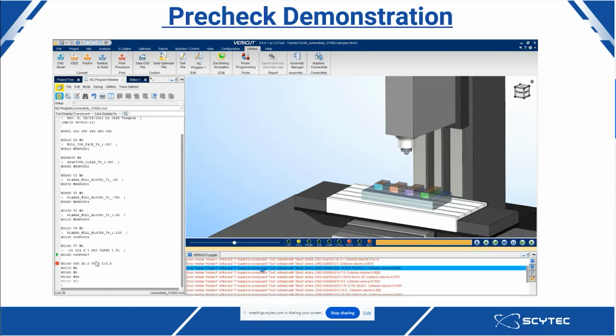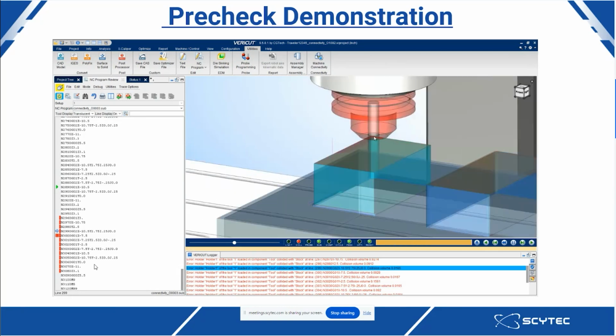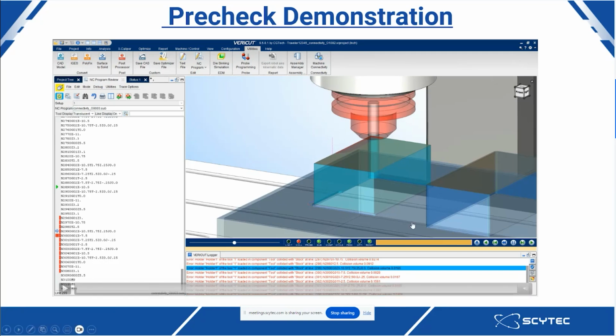So as we fast forward here, you'll notice there's a variety of errors that popped up down at the bottom. And if we zoom in here using VERICUT's program review, we can notice that shortened tool created a bit of a problem. It looks like we have a little bit of a rub on the part with the holder. So we're not going to be able to use that shorter length. So that's really the functionality that you have within Precheck. You're able to run that operation or run a Precheck down on the shop floor as kind of a go, no go. And then the NC programmer has functionality where he can go in and further investigate and see if there's any issues here within VERICUT and make adjustments as needed.